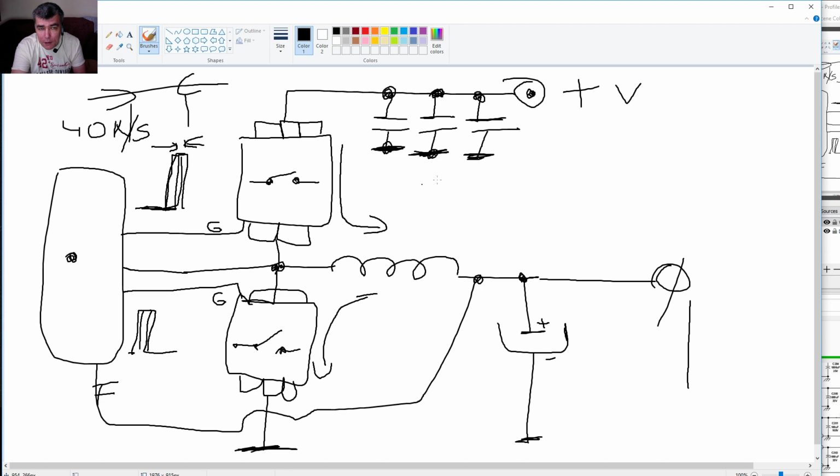But like I said, the problems are on this capacitor, because all this switching involves high currents, and it will be even here. That's the reason why these capacitors are here, to cut down all these spikes, because the signal I will have here will be something like that. That's my signal.